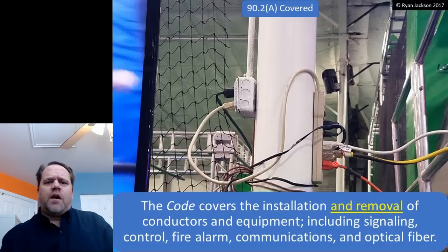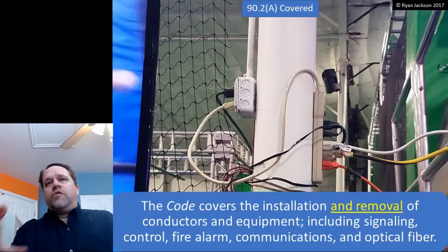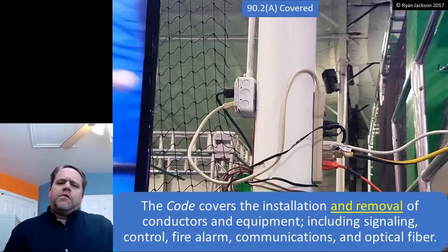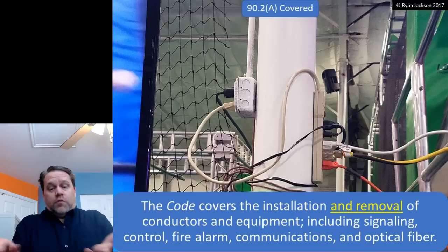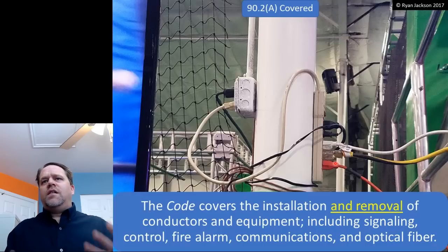Let me give you another example. If I go to Article 400 and 400.12, it says that cords are not allowed to go through doorways, windows, walls, holes in the ceiling, things like that. So what happens when I'm vacuuming my floor at my house? I plug my vacuum into the hallway, and the cord of my vacuum goes through a doorway. Is that a code violation? I mean, the code says, hey, look, cords can't go through doorways. So is that a violation of the code? No. The code doesn't tell you how to vacuum your house. The code tells you how to install electrical equipment. So that's not a violation because that's not an installation.